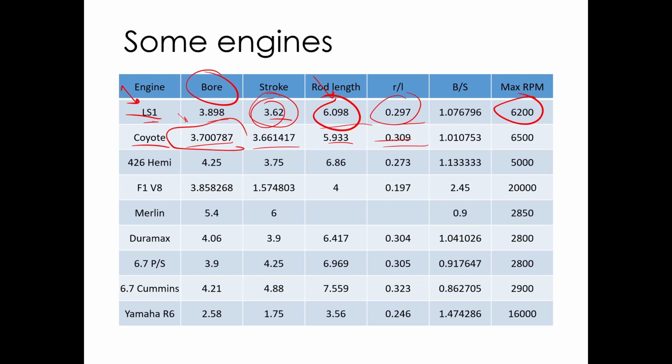It all goes back to a decision made back in the early 90s, whereas GM with their LS1 engines used a lot wider bore spacing and are able to get by with a bigger bore. Right, small changes in bore make big changes in area because it goes up with bore squared. So again, maybe adding an inch of length to the engine would have given Ford a huge amount of flexibility in their displacement.